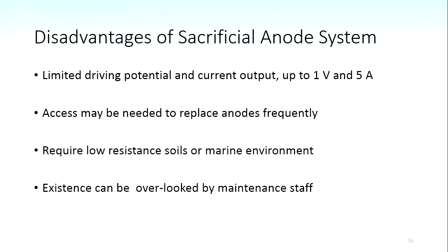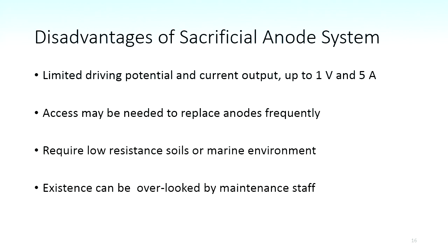And we started looking at the sacrificial anode systems, the galvanic corrosion effect essentially, and we went through their advantages and disadvantages. And one of the main problems with the sacrificial anode system is that the applied voltage is never very high, and so the resistance effects in the system become significant because all these systems obey Ohm's law.